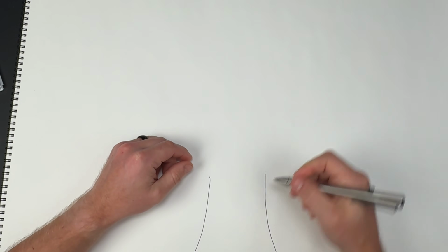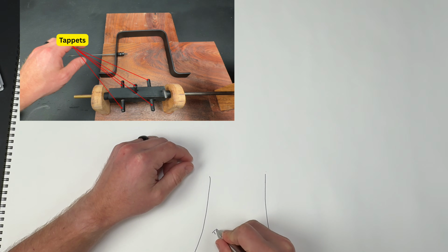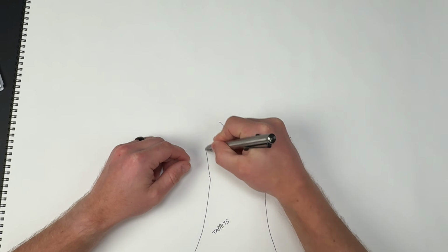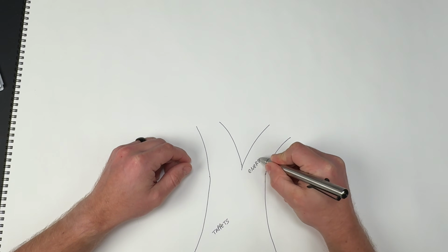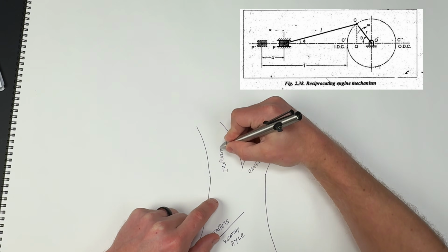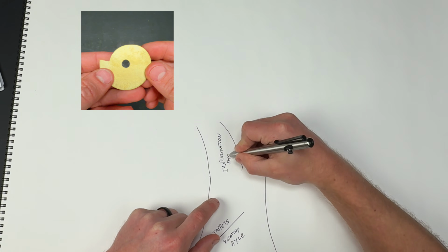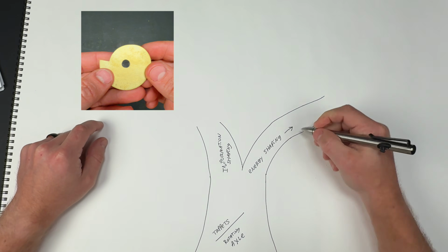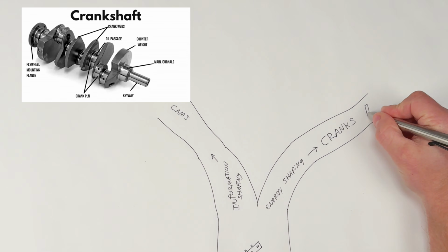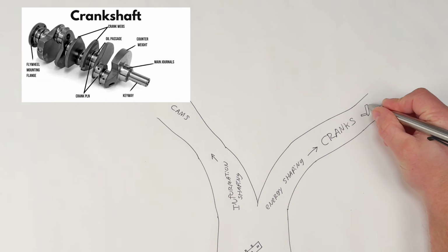We will start with the tappet here at the bottom, as it does both power delivery and basic memory in the form of timing. Out of that main trunk, the early rotating systems of the tappet and axle split into two main branches: energy shaping in the form of the crank, and information shaping in the form of the cam. The crank paves the way for the crankshaft, which is a shaft with one or more cranks that convert reciprocating motion to rotational, or vice versa, across multiple linkages.